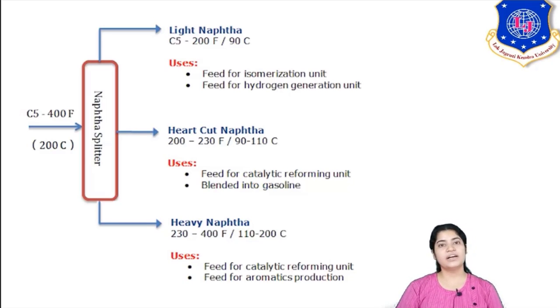Naphtha, as we discussed, has a low carbon chain, with normal paraffins. Whatever you get from up to C5 to some C8 carbon level is naphtha, the raw form of naphtha. So there is light naphtha, hard cut naphtha, and the middle and heavy naphtha. Different naphthas have different uses. Some are used directly as a blend into the gasoline. Your finished form is the gasoline.